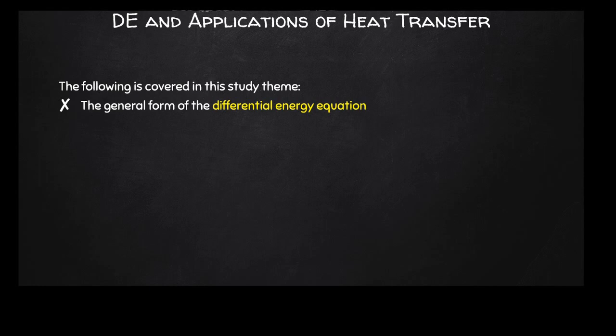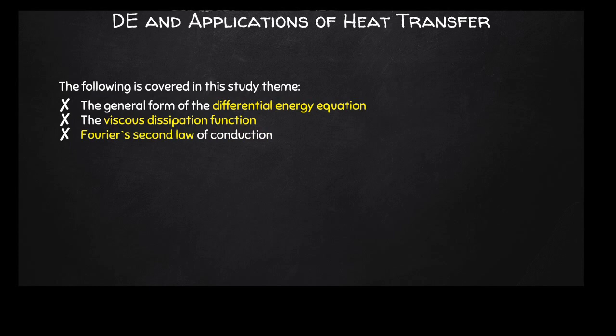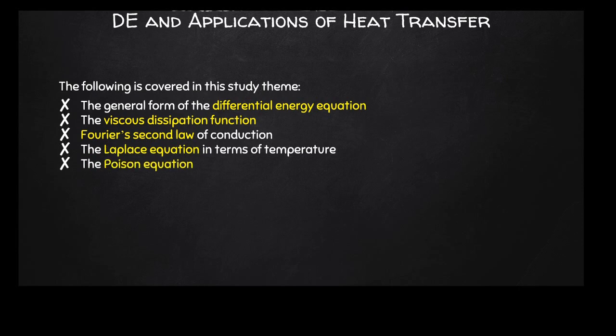We will also be introduced to the viscous dissipation, which we will then come back to in subsequent study themes later on. Special forms of the general differential equation of heat transfer are also introduced in the study theme, namely Fourier's second law of conduction, the Laplace equation in terms of temperature, the Poisson equation, and later we will also look at some common boundary conditions that we may apply to this set of equations for their simplification.